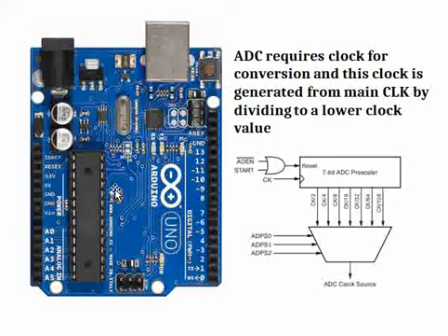Now, this means we need to generate that particular clock for the ADC so that it can operate at that lower frequency. So we have to somehow scale down the clock before using it. To scale it down, there is something called a prescaler inside the microcontroller. This is not related only to ADC. For any other peripheral inside the microcontroller, if you want to generate a lower clock to that peripheral, you have prescalers.